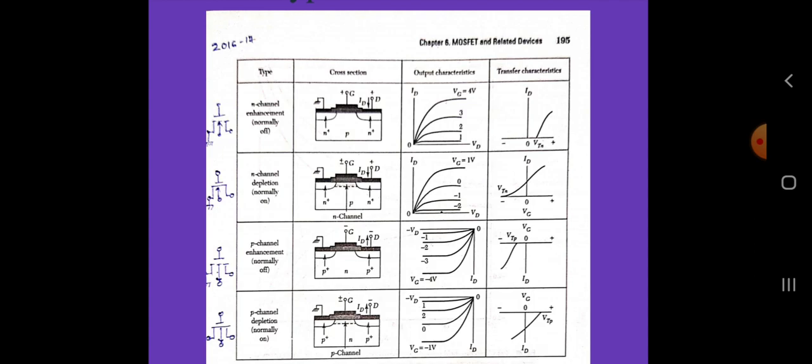When a reverse bias is applied between the substrate and the source, the depletion region is widened and the threshold voltage required to achieve inversion must be increased to accommodate larger Q_SC. These factors in turn cause a change in the threshold voltage, where V_BS is the reverse substrate source bias.